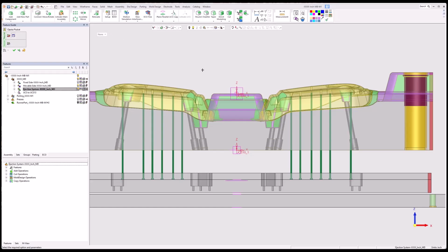The reason for that is the mirrored pins get the information from pocket from the original pins, and as soon as I select even one of the mirrored pins, it locks out the options. Okay, so I'm just going to go back to the first step. I'm going to unselect all the mirror pins, middle button.